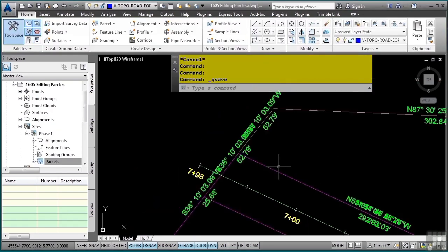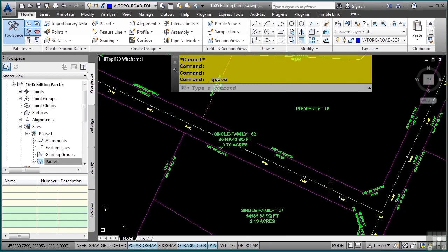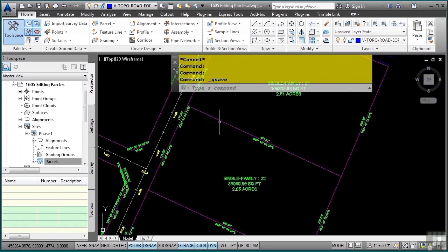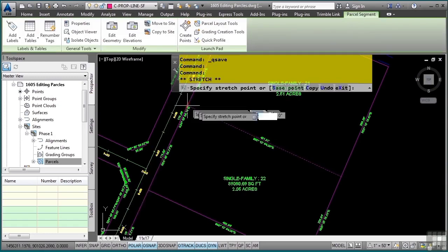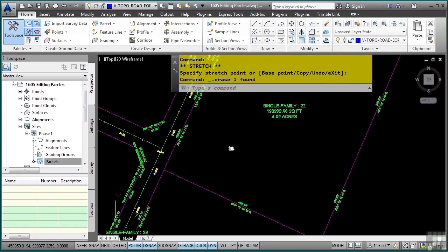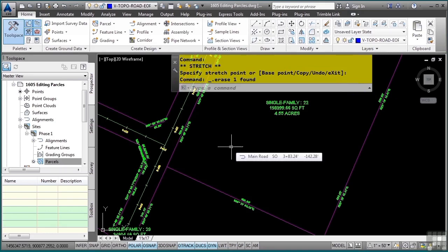Now, let's say I want to edit one of these other segments down below here where I used the Slide Line Create tool. I can just select these here, and simply using the grips, you can adjust all these, and notice again how everything updates automatically. In fact, if I delete this segment, everything also updates as well. Just some really powerful and easy tools to use.